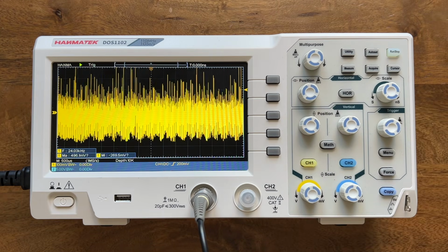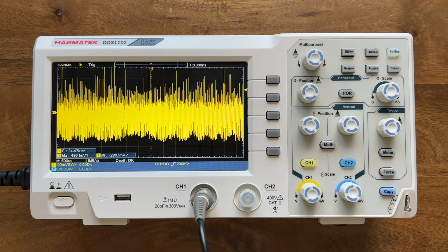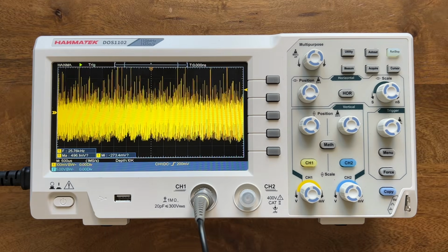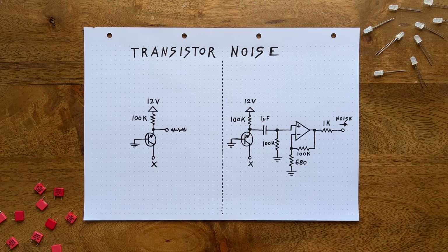That does look pretty noisy to me, though the signal's volume is really low. So we should probably try to amplify this if we want to listen to it. Before we can tackle that, we have to do the same thing we just did on the oscilloscope. Center the signal. That's because our amplifier needs enough headroom to be able to work properly.